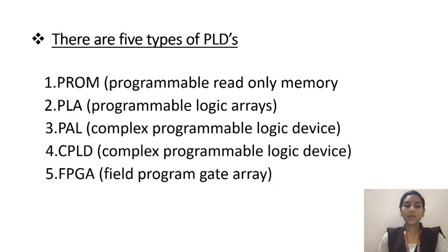Number one, in SPLDs we have three types of devices. Number one, programmable read-only memory. Next, PLA, programmable logic arrays. PAL, programmable array logic. So these are the three devices present in SPLDs. Let us see what these are, how they are used, their logic diagrams, and what components we use in them.